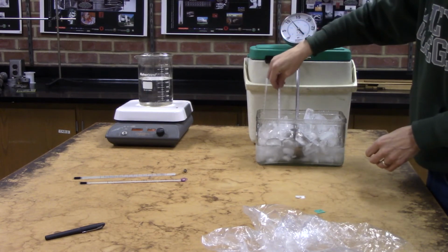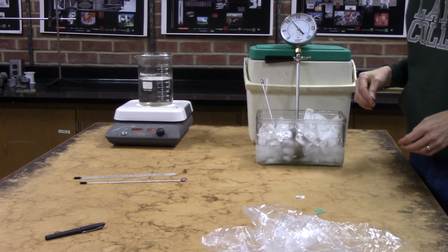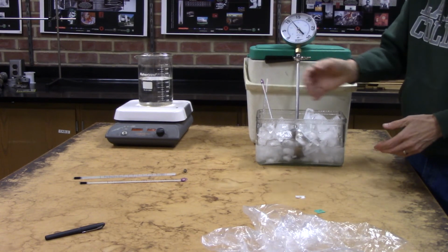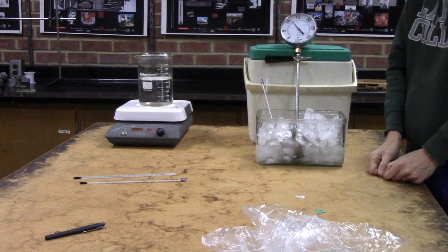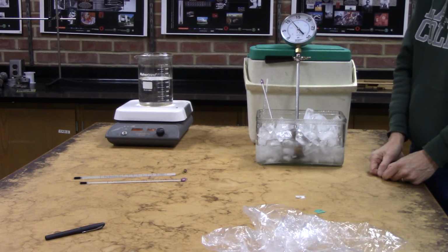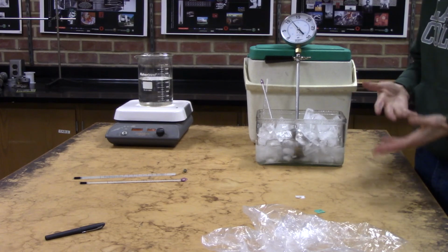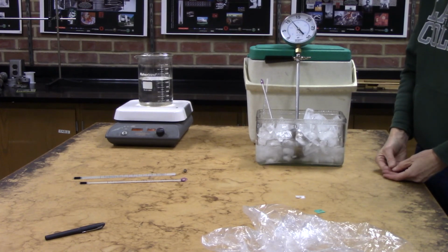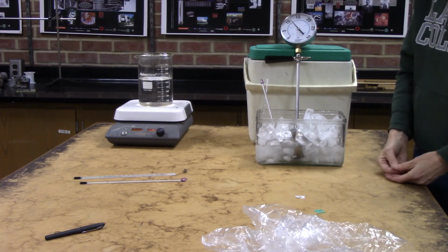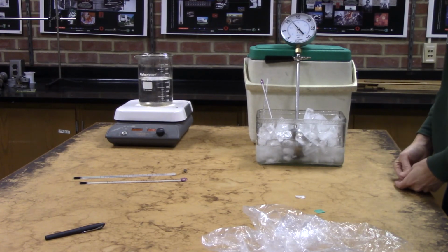So our thermometers do have limitations to them. And just setting a whole series of our thermometers next to each other, you can see up to a Celsius and a half difference between them. So with different experiments that we're looking at, we have to take that into account. Always remember that it's kind of plus or minus 1 Celsius in our thermometer uncertainties.